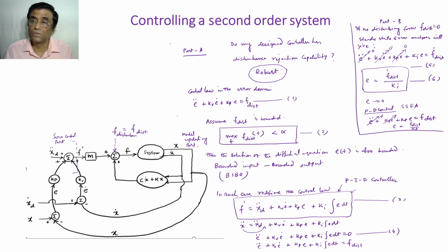However, the PID controller now has 3 degrees of freedom, Kp, Kv, Ki. So for designing a stable controller, Kp, Kv, Ki values are to be selected properly. Here you cannot just simply put the critically damped condition and crank out Kv equal to 2 root Kp.